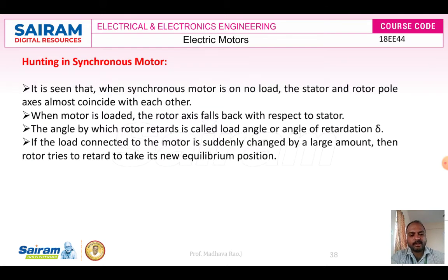Hunting is a main disadvantage in a synchronous motor. When there is a no load condition, the rotor gives oscillations, the rotor speed oscillates, and the rotor gives more oscillations. To decrease that, we need to have damper windings in the synchronous motor.